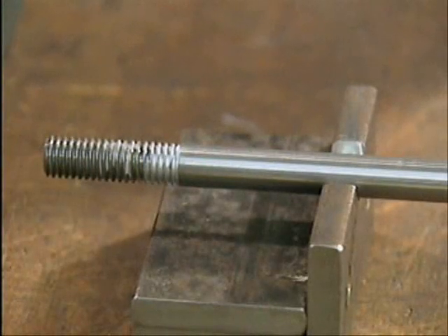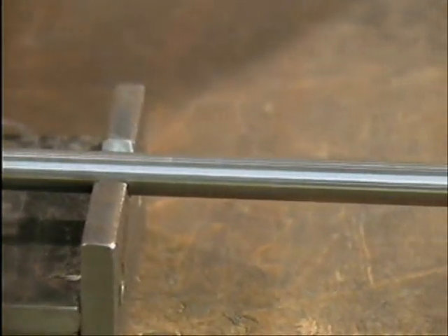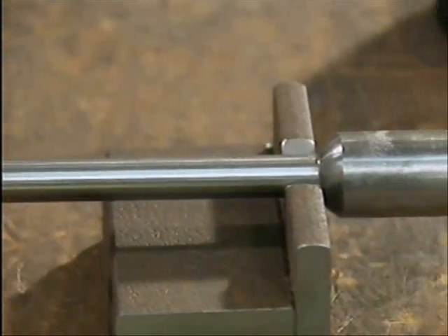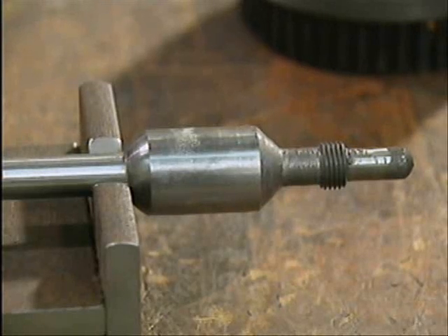It's also important to check the straightness of the valve stem, because a bent stem is a common cause of valve malfunctions. A bent stem can prevent a valve from opening, or it can keep an open valve from reseating properly when system pressure returns to normal.